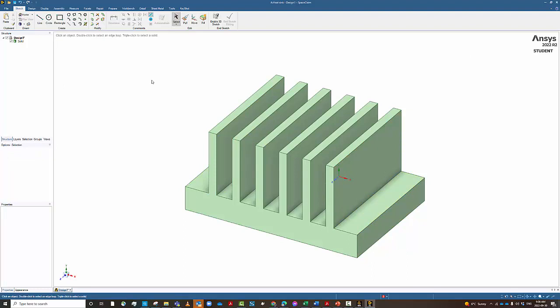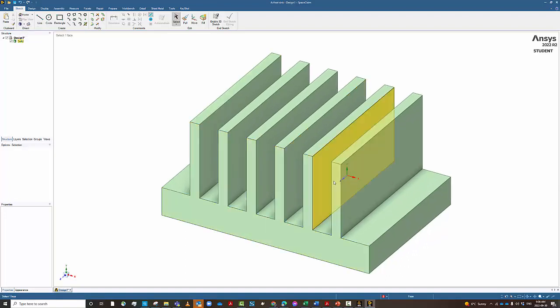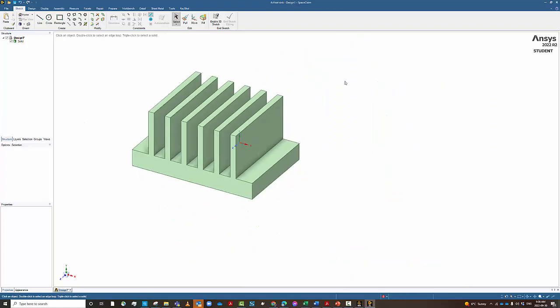So when you do extrusion, you can do extrusion if you are on the XY plane, as we are. You can ask the extrusion to be in the positive Z, in the negative Z, or around the zero. So if you want 15, it could be from 0 to 15, or from 0 to minus 15, or from minus 7.5 to 7.5. You can do a lot of control in the extrusion module when you see the options for extrusion.